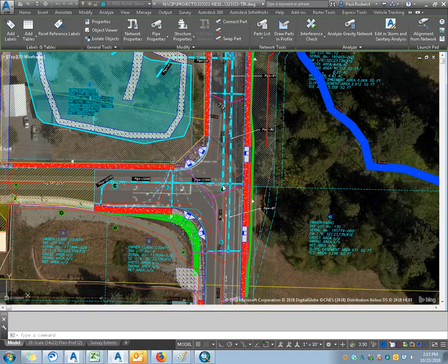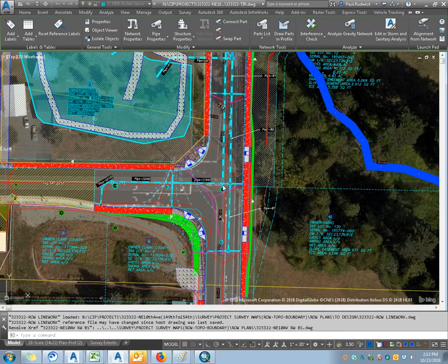However, we're raising the road elevation several feet in places. So we're going to pull off the top cone and possibly the top riser section and put a new one on. We're not going to replace the whole thing.